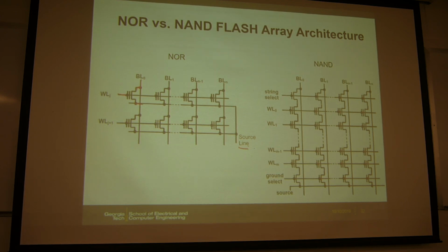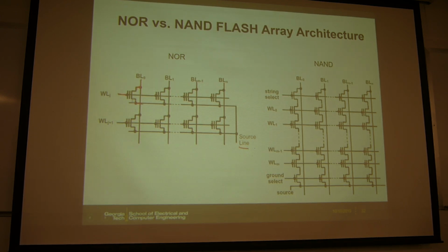So this is like your DRAM, because in DRAM the other side is to the common plate through that capacitor. So it's the same as the DRAM. And this is called NOR because from the logic circuit point of view, you have the parallel NMOS structure, which is NOR, right? For the pull-down network, you have the transistors in parallel. So here you have those transistors in parallel.